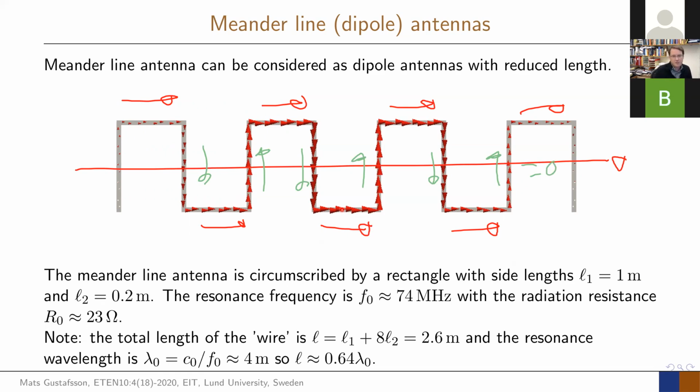They cancel each other. And the reason for this is that the total distance here is basically less than lambda over 2, because the full wavelength dipole would be lambda over 2 approximately. And now I have made the wire that length, so I make it shorter. So I get a dominant radiation from a dipole. It looks like a Hertzian dipole.